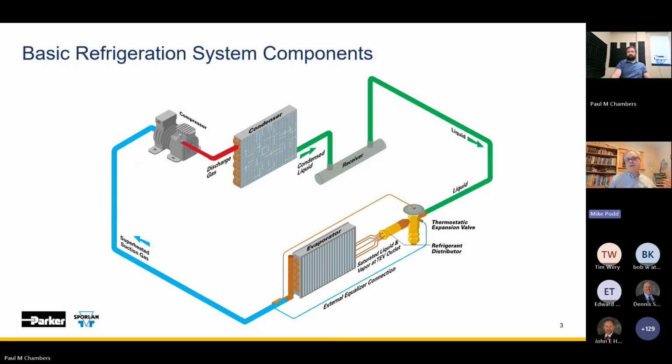Now on an air conditioning system or a refrigeration system that uses an indoor condensing unit, the condenser is always going to be in the same ambient conditions. But when the condenser is outside and something that was sized for 120 condensing is now working at 80 condensing or substantially lower, that condenser is now oversized for the application.